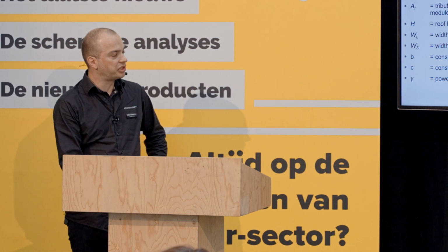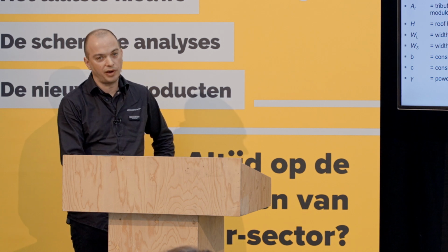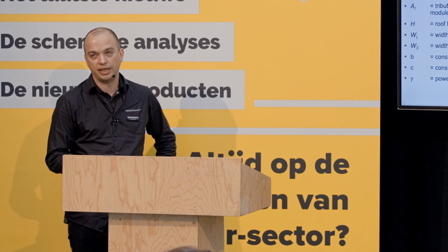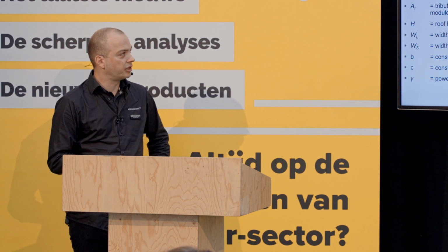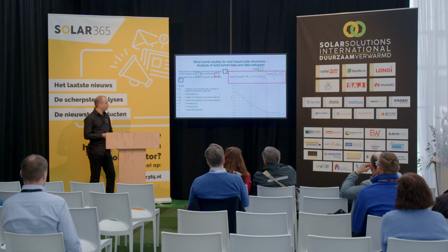There is a term which is composed of the load sharing, circled in green, or the tributary area, and it is divided by another term which is representative of the building size. So that's why the normalized tributary area is non-dimensional.